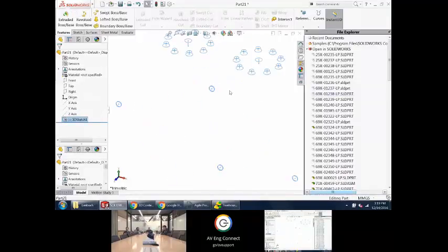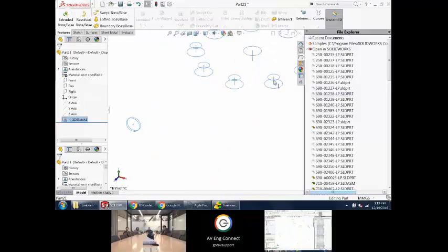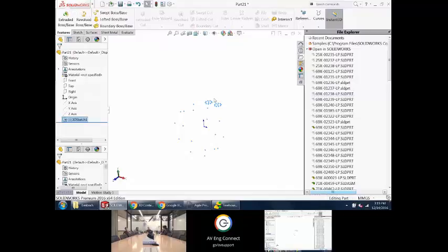It's just copied where the tops of the distributor caps are and where the tops of the spark plugs are. And then I was able to just run splines in between those. But I did a 3D sketch, convert entities, copy the 3D sketch and paste it into another part. No external references, yet I have the information on where every one of those is in space at the assembly.